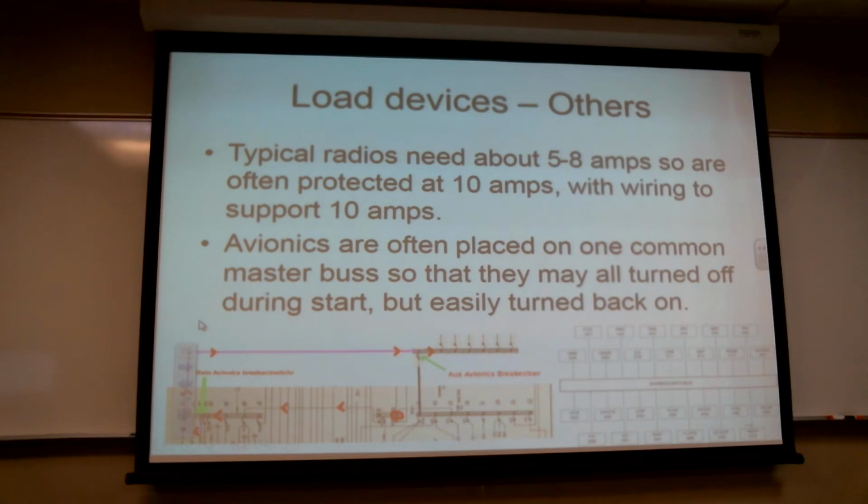So let's say the cold cranking amps is 300 amps, the starter is 300 amps, but that inrush current took it up to 700 amps. So initially that battery would drop all the way down to 1 volt or half a volt for a few thousandths of a second until the inrush current starts changing. Then it's going to come surging back up. So now you may end up with an onset surge.